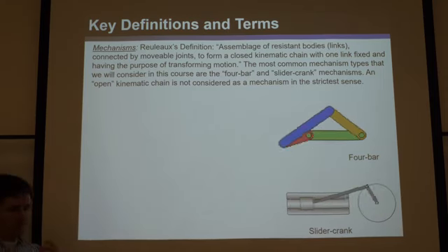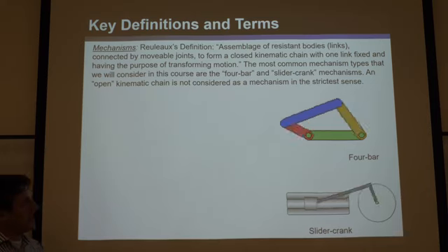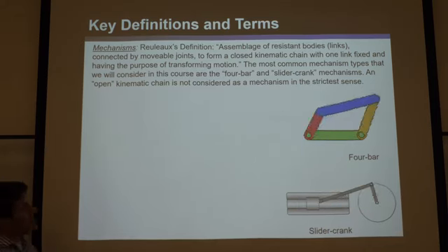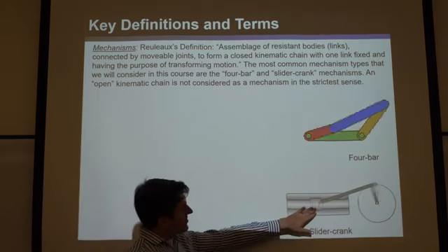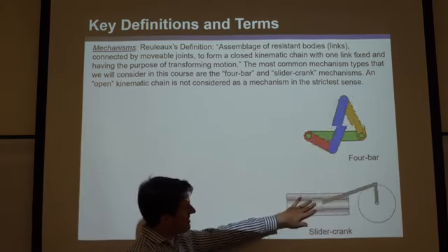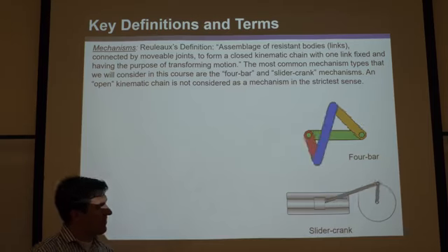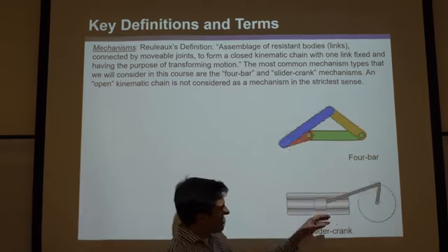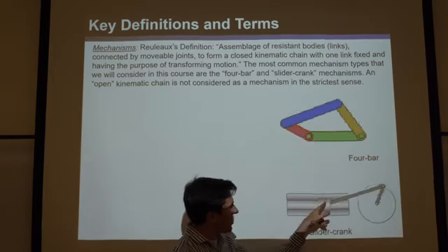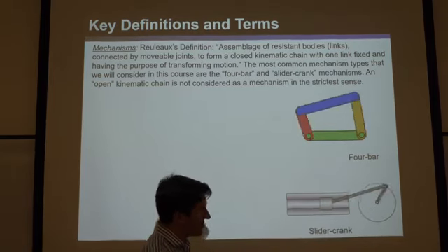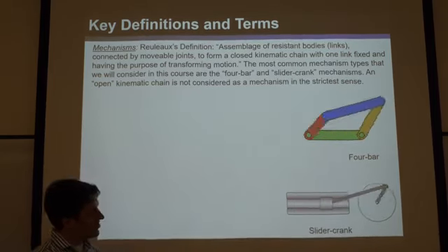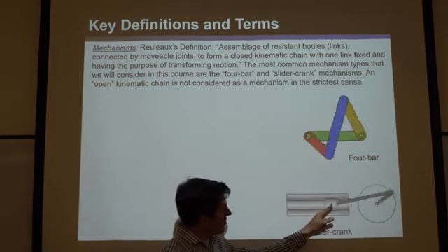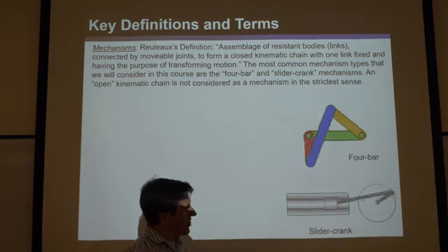So we're going to review that a lot and do some examples and you'll be able to tell me what is a traditional mechanism. This one is also famous. We've talked about the 4-bar, but this is a slider crank mechanism. And of course it consists of rigid links. You can see here there's the ground, there's these 2 bars, and there's this piston that pushes through a prism or translation joint. And you can see there's a rotational or a pin joint here, and at the two parts there.